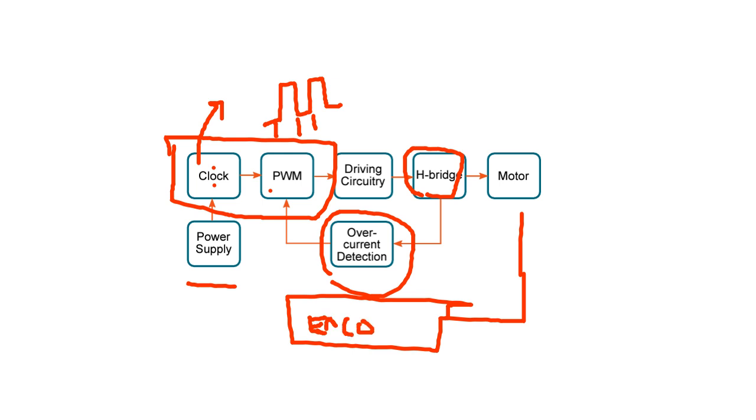This means that you can measure the position and speed of the motor. For example, in white goods, you have a reference speed value of 100 RPM, revolutions per minute. Okay, if you want to reach 100 RPM, you must follow the feedback speed. This is called a closed loop system. Good.